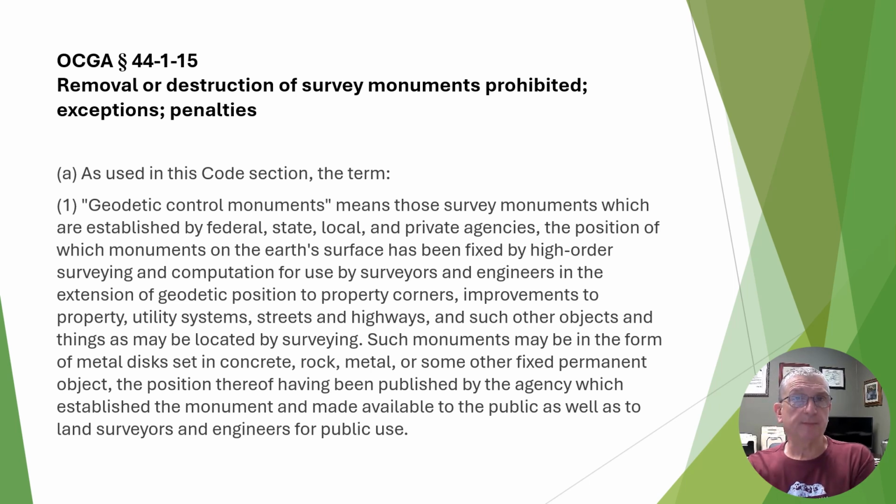It can also be applied if there's a DOT project or a pipeline project perhaps, or some sort of waterline project, and they've set intervisible control points along a long linear project. Those control points would likely be a geodetic control monument. And so the reason we mention this is if they are removed or destroyed, it's a violation of this law and there are penalties.